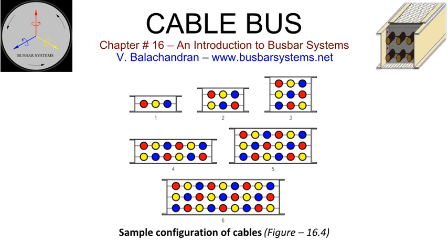Expansion joints. Expansion joints may be provided to isolate vibrations and compensate for minor misalignment in layout. They are located across a building expansion joint. Most of the bellows are made of either neoprene or EPDM, ethylene propylene diene monomer, rubber. Terminal adapter boxes. Most often, a cable bus will terminate on transformers located outdoors or switchgear located indoors. Termination adapter boxes shall be made of the same material as that for cable bus.